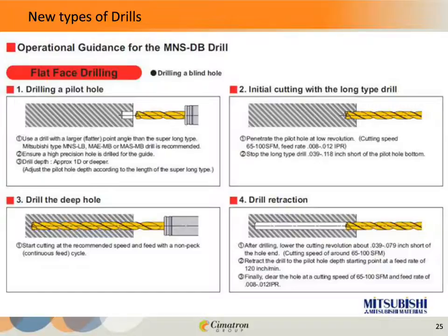Maybe a center drill won't be necessary, but we're going to do a pilot hole. And generally speaking, the pilot hole should be about 1 times the diameter.